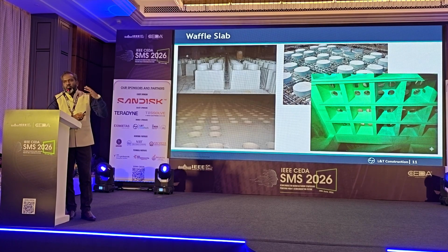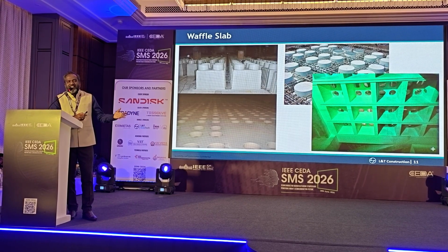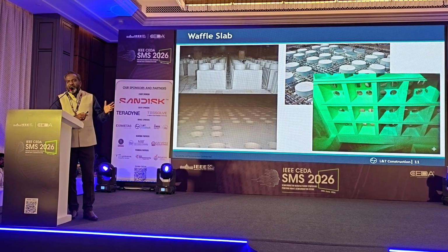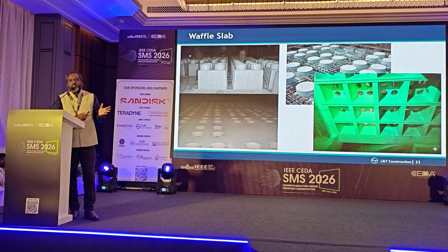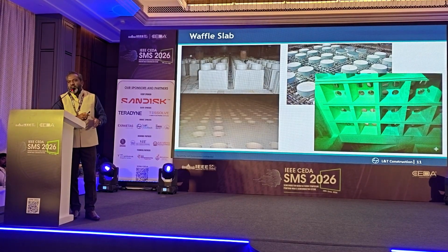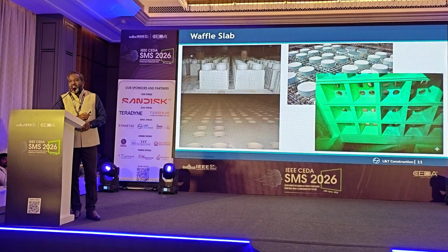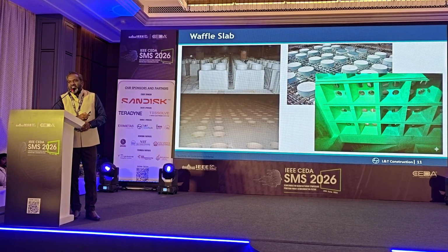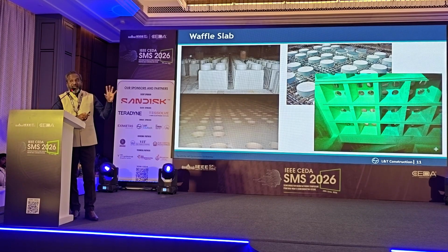I don't want to get more into it. Just to give you an idea, it is not about earthquake vibration. We are talking about somebody walking next to it is a vibration, right? A highway close to this fab is a vibration. In Taiwan, I come to understand that high-speed rail was diverted from Hsinchu because there were so many fab plants and that was not designed for this vibration. High-speed rail diverted for 20-30 kilometers away. So that is the vibration that we are talking about.